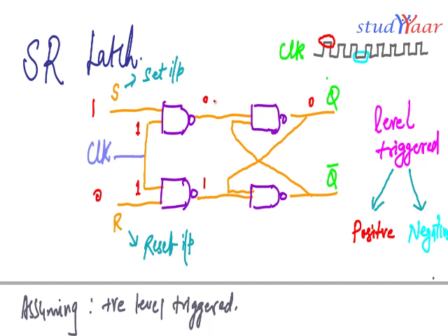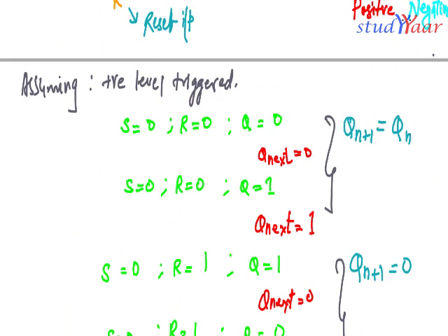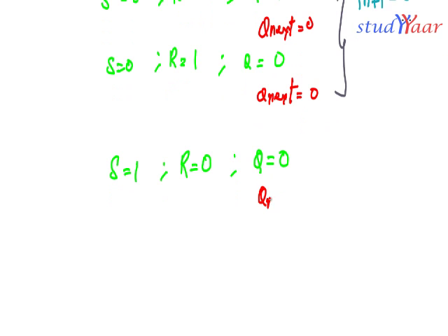Okay, now I have a 0 over here. Okay, and whatever be the input, 0.x bar is going to be what? This is going to be 0. Okay, so 0.x bar is going to be 1. So what happens is this Q becomes 1, okay, and this 1 is over here, and 1.1, the whole bar is 0. So my Q next is equal to 1, okay.